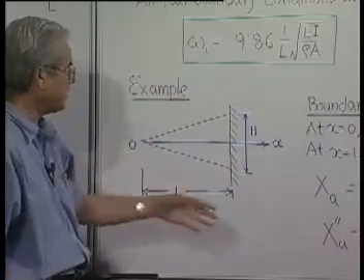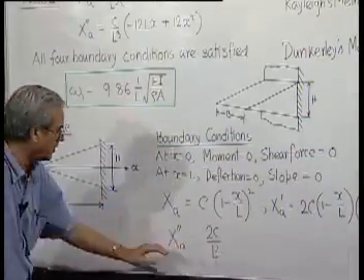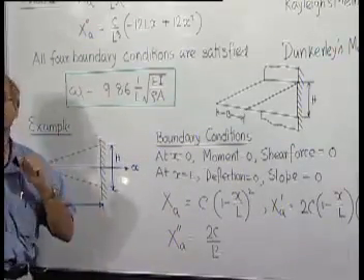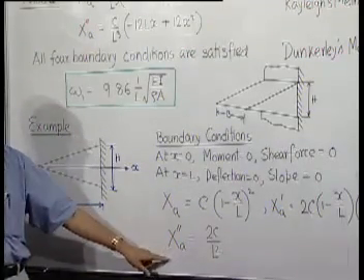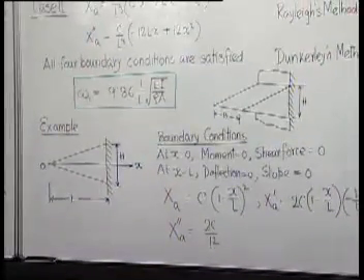So whatever may be the value of this, moment applied will be not just this, but you have to take care of EI. So that EI is 0 because I is 0 at this end. Therefore, bending moment at this end is 0, though the second derivative is not 0. So this is a very important point to observe.